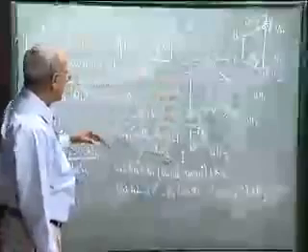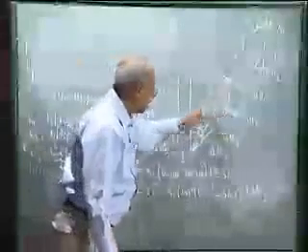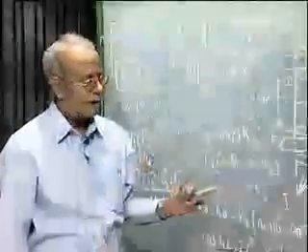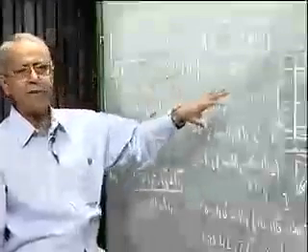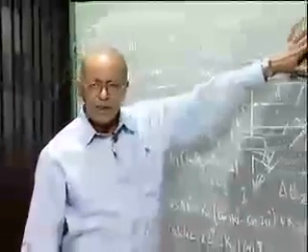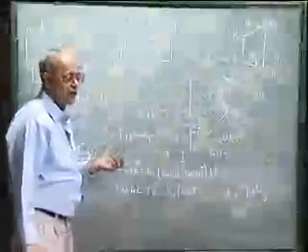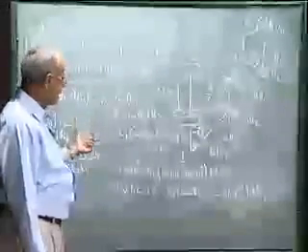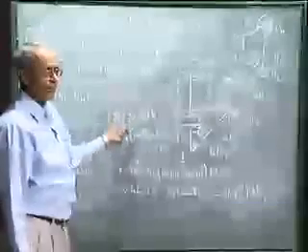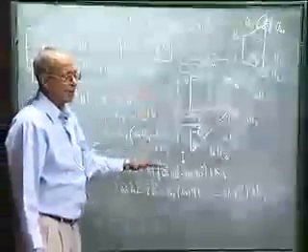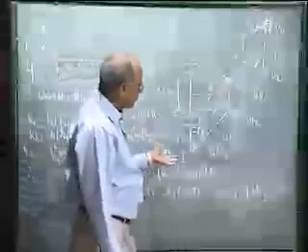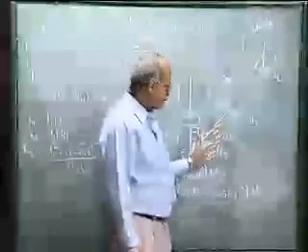But for all other values of the radius of curvature of the path, this steering condition will not be exactly satisfied. So this is a much simpler mechanism than Davis gear, but it is obviously not satisfying the steering requirement for all values of the turning radius. It is satisfying only for a particular value of the turning radius, and for all other radii we are almost ensured that the deviation is not much.